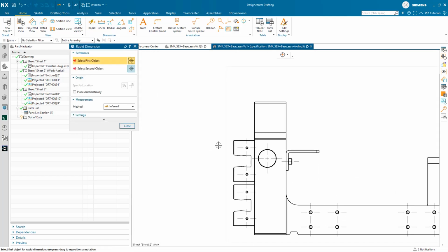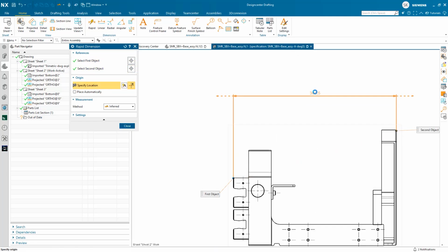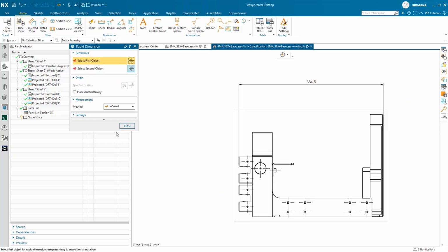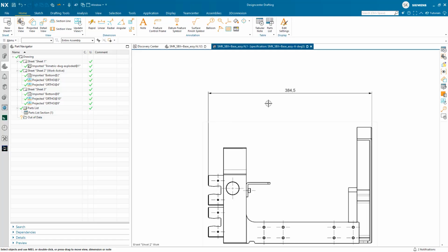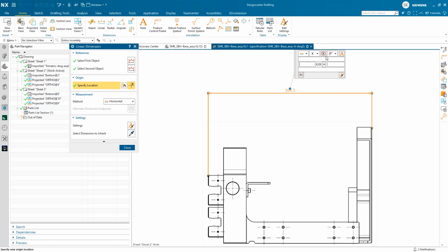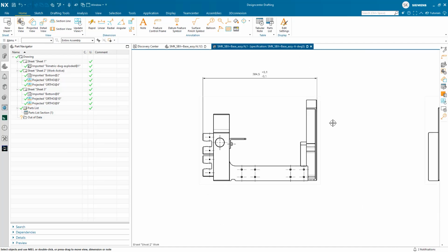I want to create some assembly dimensions that are critical for the overall assembly information required on the drawing. So we can add the dimensions. Once a dimension is added, we can come back and correct the tolerance, or add a tolerance while I'm adding dimensions. In this case, I want to add some tolerance, making sure that some options are available. So I can come in there, add some of the tolerance and specify what the tolerance may be.